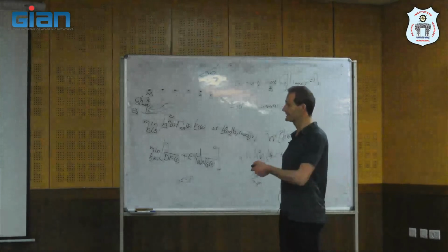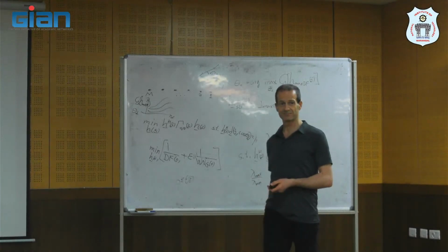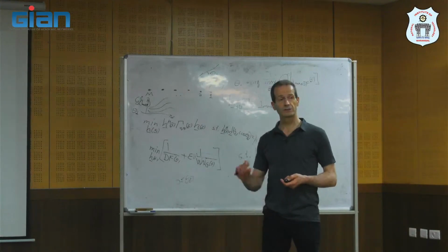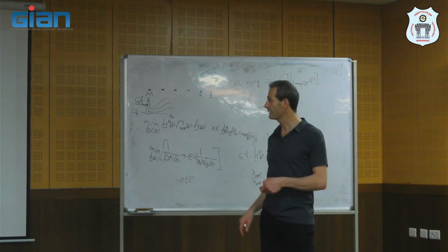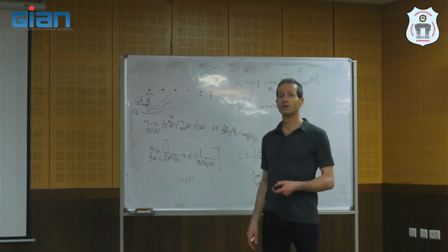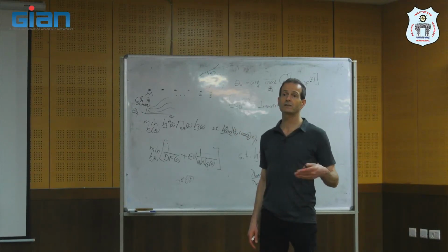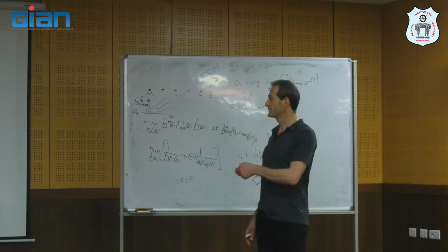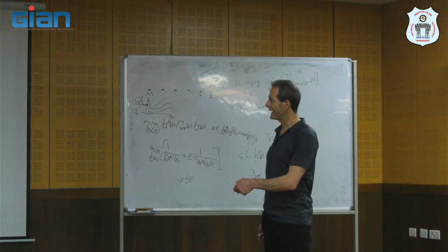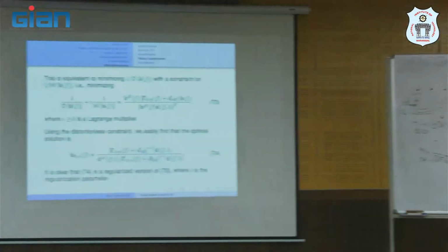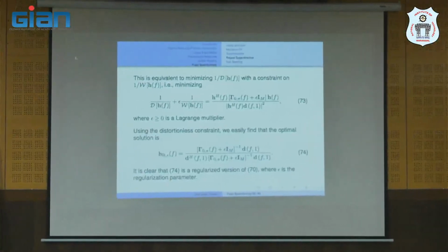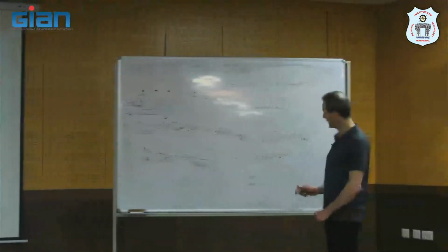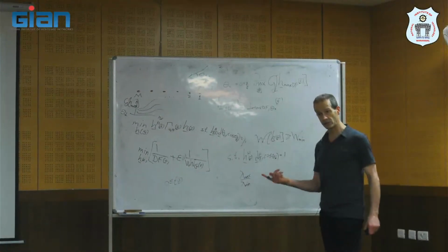Here we see that it's sensitive to thermal noise. But it makes sense. The sensitivity to thermal noise comes from this inversion of a matrix which has a high condition number. So what did we do here? We added epsilon multiplied with the identity matrix. What happens to this ratio? So instead of this ratio, we have eigenvalues.